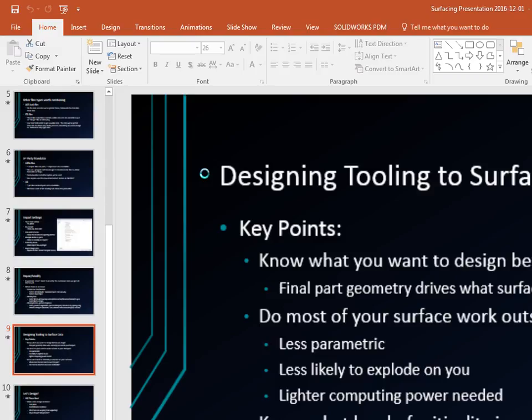Yeah, and after that on this part, basically all I do is add in some in-context features for the ones that errored out because I made that new one. Face fillet works sometimes in some areas, but it alters geometry. Especially in something like this where you've got a ton of faces, it's hardly worth picking all the faces to find out whether it's going to work, in special areas like corners where everything's a transition. Yep, that's a good point. Face fillet will sometimes do it where others won't.